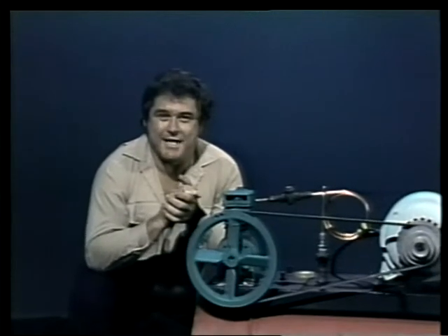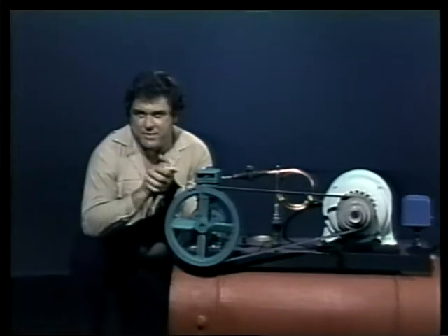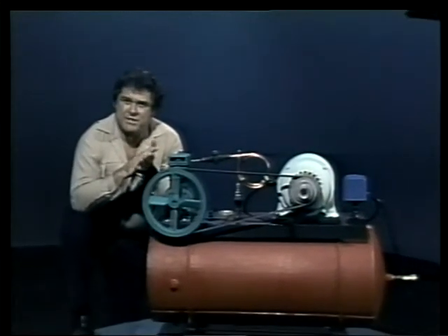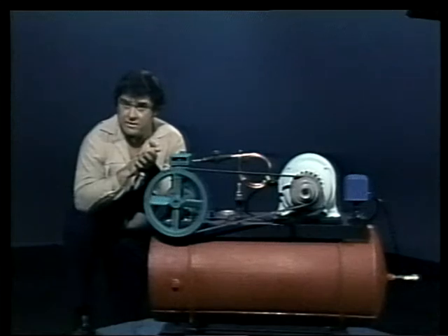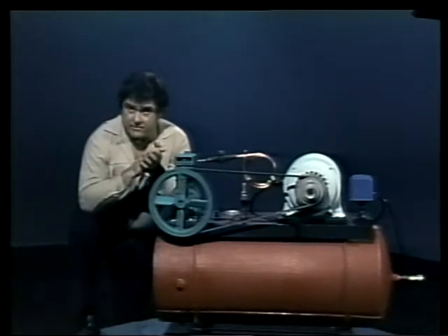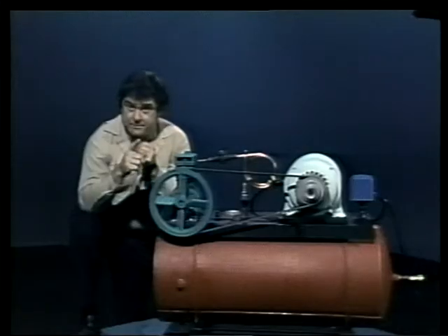So we've got 4 different ways to categorize reciprocating compressors. They can be single cylinder or multi-cylinder, single stage or multi-stage. They can be single acting or double acting, and they can have their cylinders laid out vertically, horizontally, in a V, in an L, or in a combination of these types. The layout of a compressor doesn't have a lot to do with its operating characteristics. It has more to do with the space that the machine has to fit into. But the other 3 categories do make a difference in flow rate and in discharge pressure.